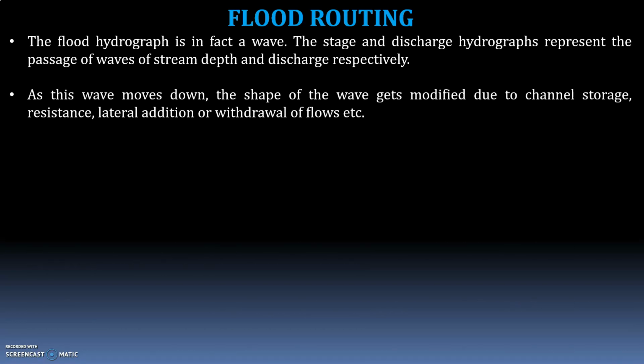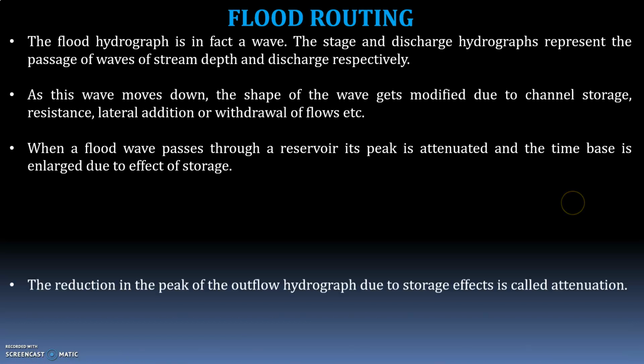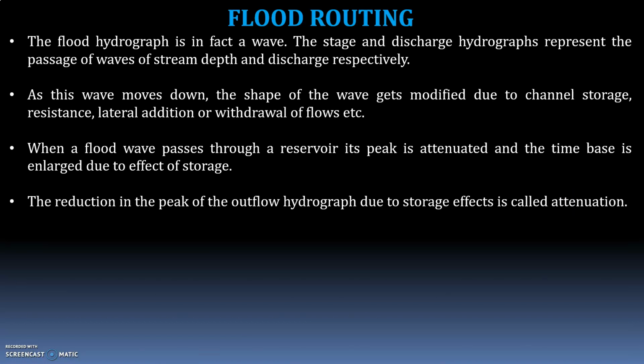As this wave moves down, the shape of the wave gets modified due to channel storage, resistance, lateral addition or withdrawal of flows, etc. When a flood wave passes through a reservoir, its peak is attenuated and the time base is enlarged due to the effect of storage. The reduction in the peak of the outflow hydrograph due to storage effect is called attenuation.